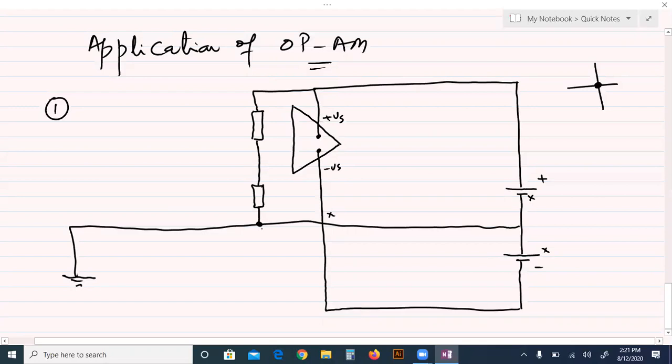Look, this is the junction here. Now, the value of each is R, both are the same value. Suppose this is a 12-volt battery. So 12-volt supply positive, 12-volt here, but here 0-volt. So this 12-volt is equally divided, 6-volt here, 6-volt here.